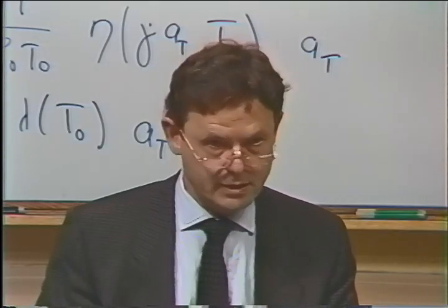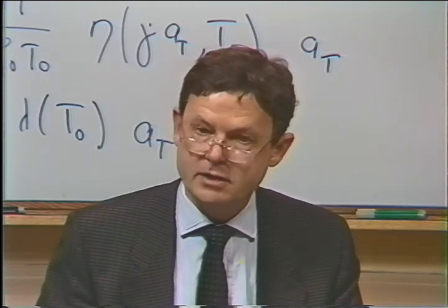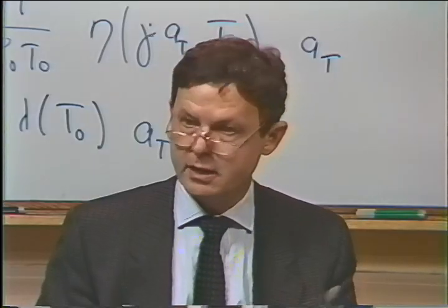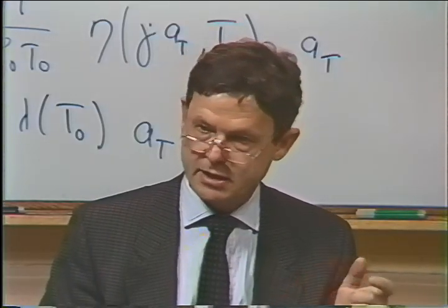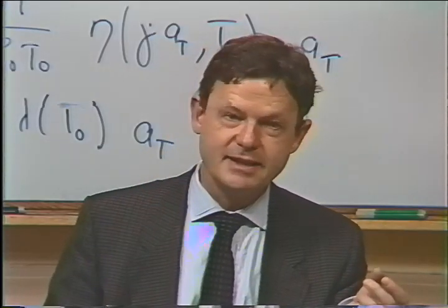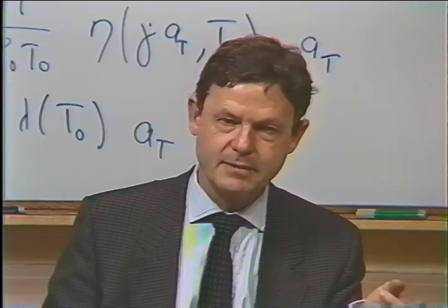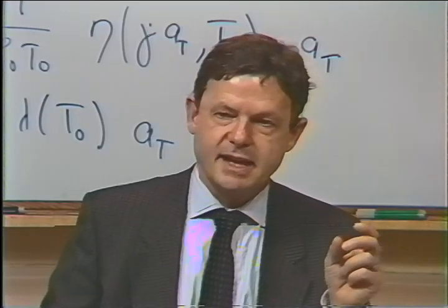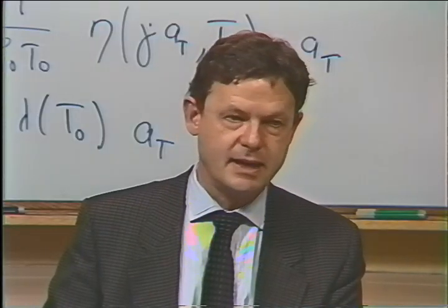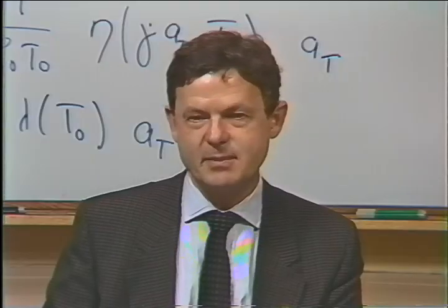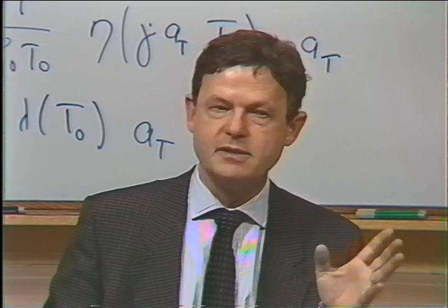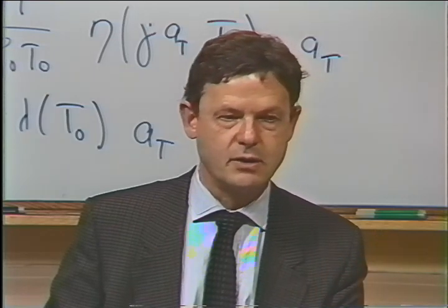We will come back to the rheometry correction to calculate the shear rate at the wall in the capillary. We already know the shear stress at the wall, so having shear stress and shear rate, we can determine the viscosity from our measured values in the capillary rheometer. We also will discuss a second way of determining the shear rate. There's an even more elegant, simpler way of determining the shear rate in capillary rheometers, which gives you the value instantaneously in a very simple fashion.